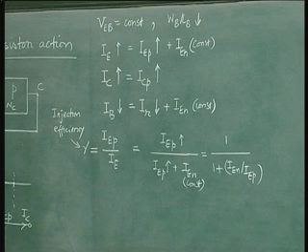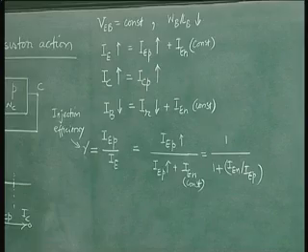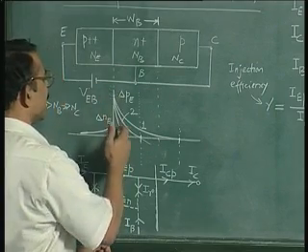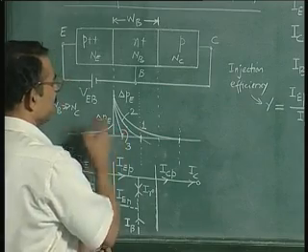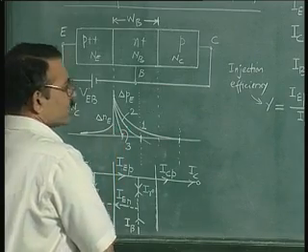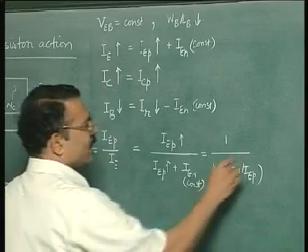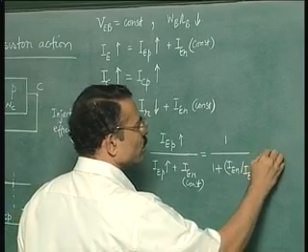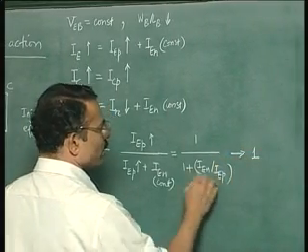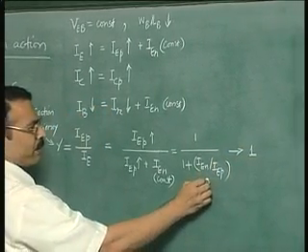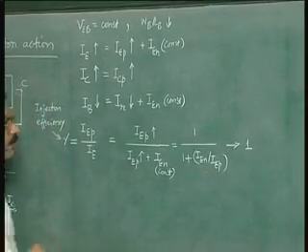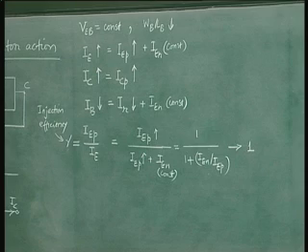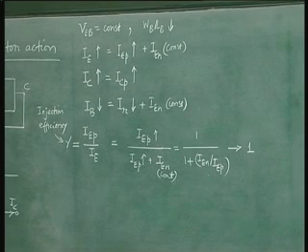And for the limiting case of very small WB, when the WB is very small, you see that the slope is very large. So your IEP is much larger compared to IEN. So therefore we can say that this quantity tends to unity, because this quantity tends to 0 as WB is reduced. So injection efficiency becomes close to 1.